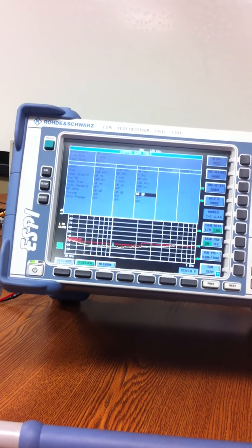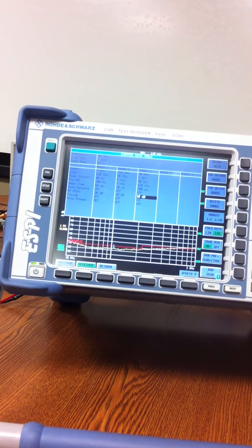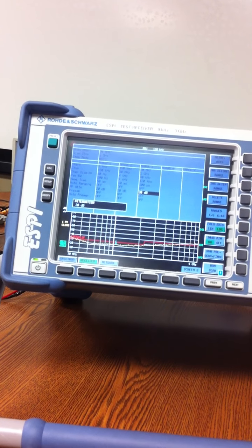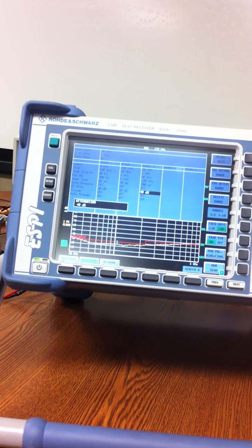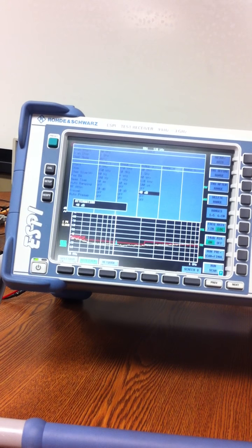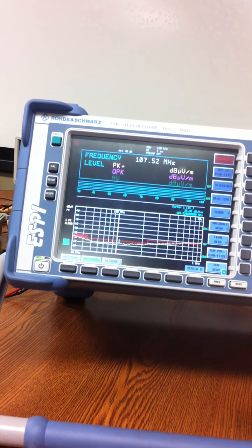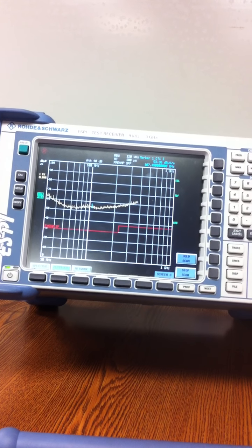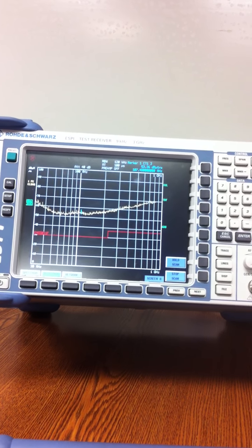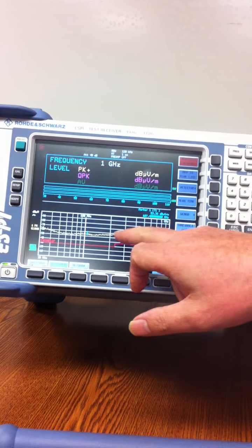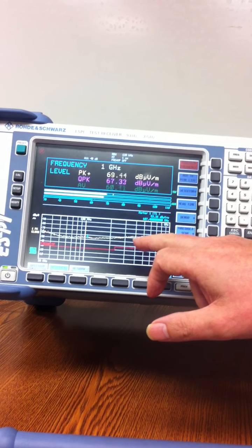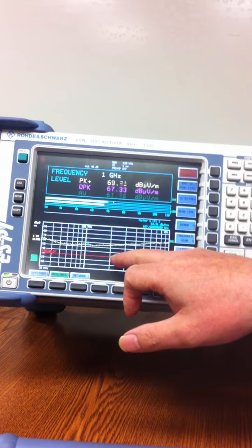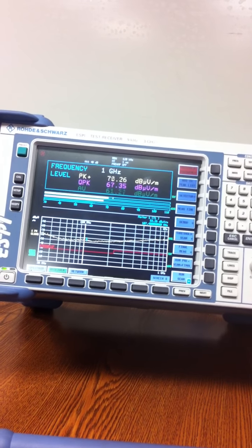If you go to a higher value here, press enter, and you can see the changes. Go to 40 dB. Okay, it's done. And we run the curve again. See what happens? It pushed you up. It tells you that you have a much higher noise floor in your system that is high above your limit line.